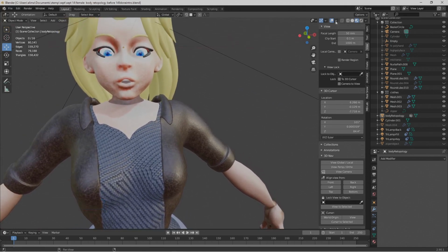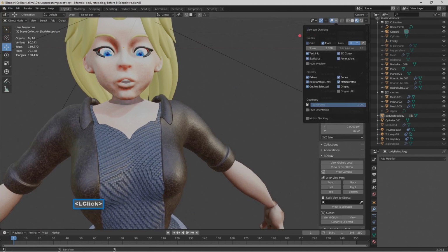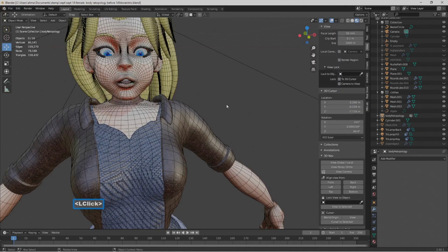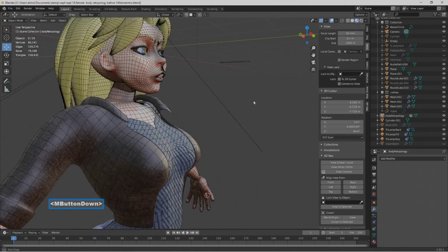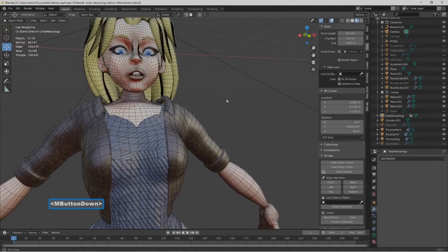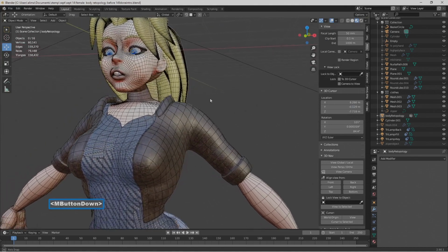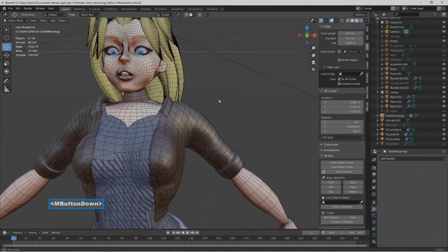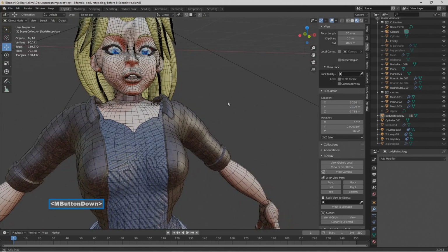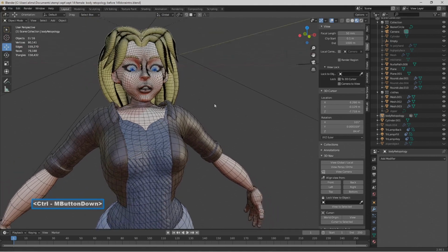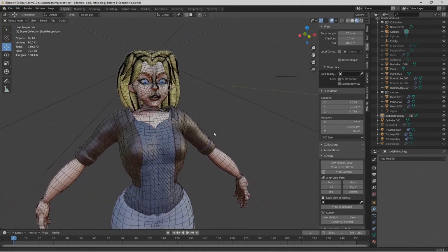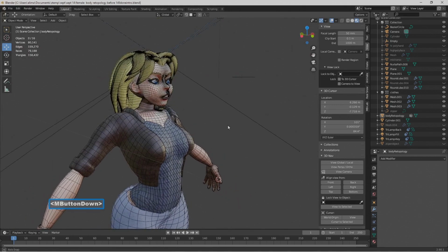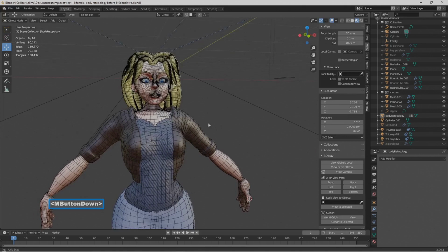As you work your way through the tutorial, you'll be shown how to do the entire process of body retopology. You'll be shown how to retopologize the entire torso, as well as more complicated retopology techniques like the hands. You'll also be shown how to use UV maps to set up normal maps.